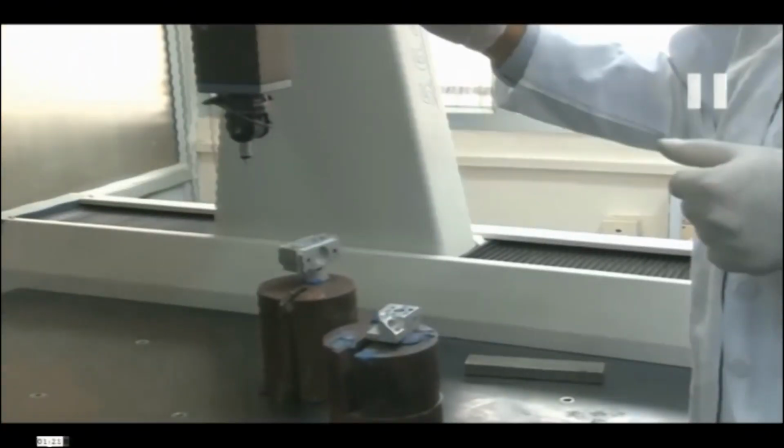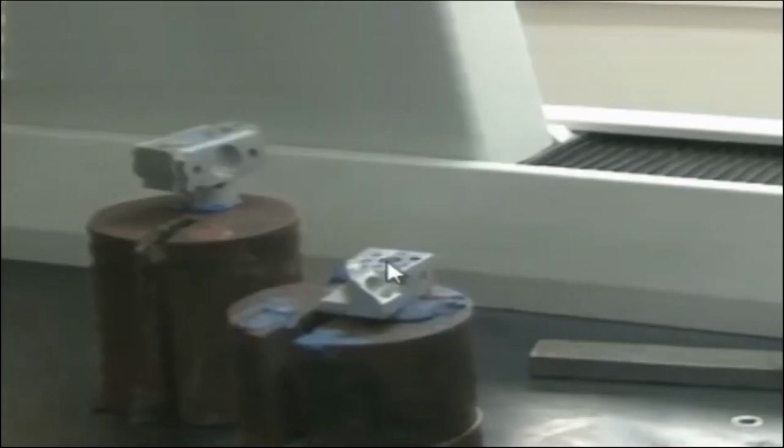It has 3 axes: X, Y and Z. This is a 3D object that we will measure using this coordinate measuring machine. We will try to measure the features of this component. You can see there are a number of circles here. There is a center circle, a center cylinder here, and then we have 6 cylinders around this center cylinder. I will first measure this full cylinder. Then I will measure these 6: 1, 2, 3, 4, 5 and 6. I will try to locate these 6 circles, not the cylinders.